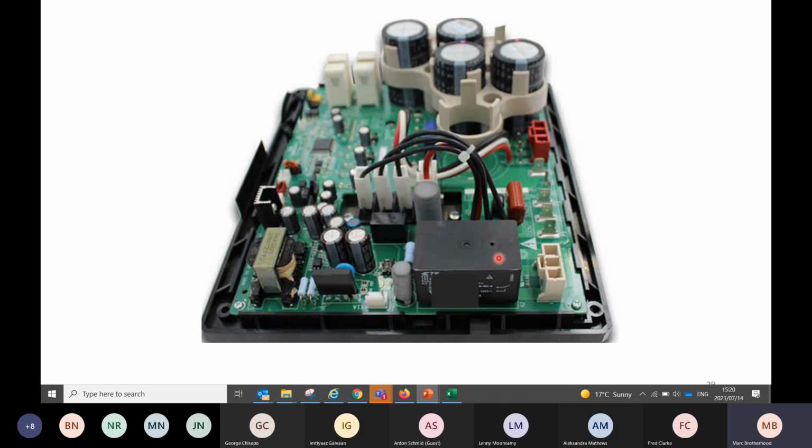But if we have a look here, we see this little tall boy. This is what you call a shunt resistor, and this little relay. My motherboard will use my one phase, my L1, to feed this relay to shut it. It'll provide my neutral return. So once these caps are charged, it'll go out my neutral wire. This will actually be my neutral plug here. It won't be on those three phases. And this shunt resistor is there to absorb any inrush current or spark to stop damage, primarily to this relay.